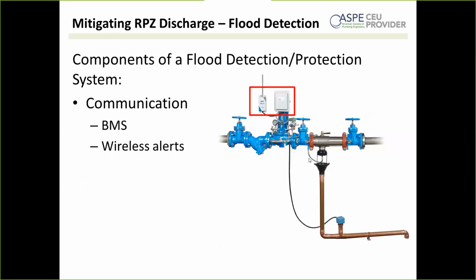Okay, and are manufacturers' air gaps interchangeable, or should they be paired with like parts? Usually they're not interchangeable. On purpose, most of these are not an NPT fitting, because manufacturers want to make it very difficult for people to block that relief valve, right? If it was, say, a 2-inch NPT, and somebody who's maybe not well acquainted with backflow preventers sees it leaking, they're going to find a way to plug it. So for that reason, they all are a little different.